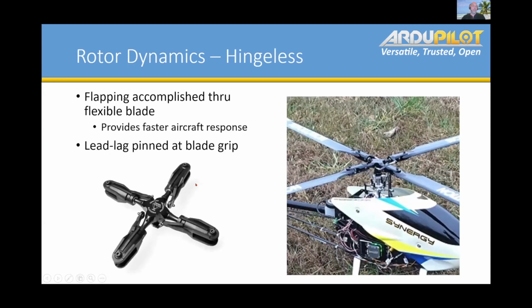Here's kind of a hingeless, what I'll call a more or less hingeless rotor in the flap degree of freedom. Basically this is a Century multi-blade rotor system, and it's mainly aluminum in the shaft here, and then there's plastic grips. But basically, this aluminum here really isn't that flexible. More or less where you're seeing the flexibility and the flapping is coming from the blade, and the inboard portion of the blade is really where the flapping is occurring there, because they're very stiff.